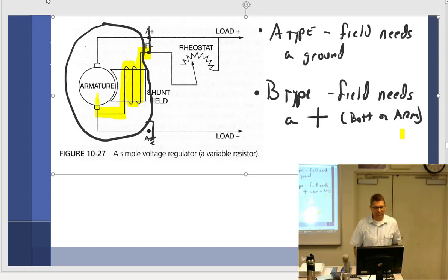Well, there I see blank stares for a minute. Oh, it will work, but it will keep on going up. There you go, it'll work. Is it regulated? No. Absolutely, completely unregulated. So what would the output as far as voltage be of this? All of it. You'll find out very quickly, and what it's going to do is heat up very rapidly. As it heats up, there's a lot of solder in the armature, so we have solder heating up with an armature that's spinning. So we have centrifugal force, so then what happens? Slinging. It starts slinging the solder out of it, and then it's going to end up looking like the slinky that's shoved in here, right?